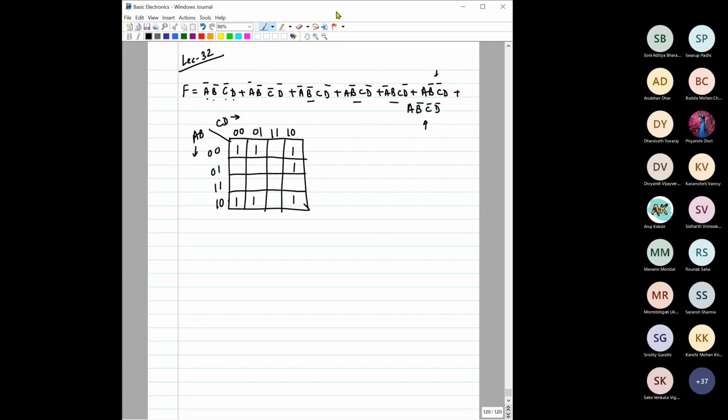Okay. So here, these two ones are there, so we can take a block of these two ones. Also, you can take a block of these ones, and also we know that as the Karnaugh map is foldable, probably we can also take it like this, right? If you fold it in this direction and in this direction, then this side will connect with this side, and you can make a combination of all four ones, right? So that way we have one group with four ones.